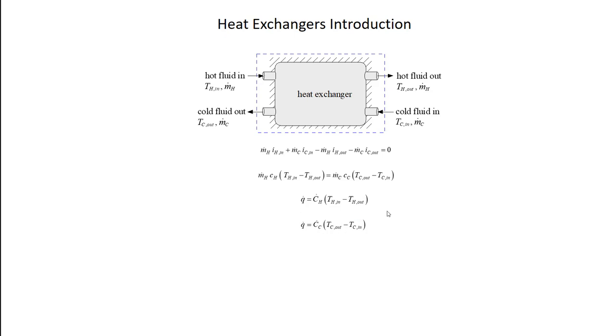All right, so these are equations that I can write down for any heat exchanger. They don't help me solve the heat exchanger problem because, if you think about a typical heat exchanger physical situation, I would have a heat exchanger, I would plumb it up to some hot fluid at T_H in, I would plumb it up to some cold fluid at T_C in, and I would want to know what T_H out is and what T_C out is. And if you look at these equations here, this is two equations in three unknowns. I don't know Q dot and I don't know the outlet temperature.